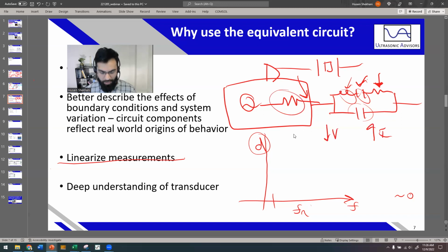So what happens in reality is that we drive our transducer and end up with this flat spot. This is the actual driver with an actual transducer. This is what ends up happening. This region is kind of constant displacement. So we can calculate things like coupling factor, and the theoretical anti-resonance frequency: if we were to keep this displacement constant, what would the anti-resonance frequency be? That also allows us to describe a transducer.